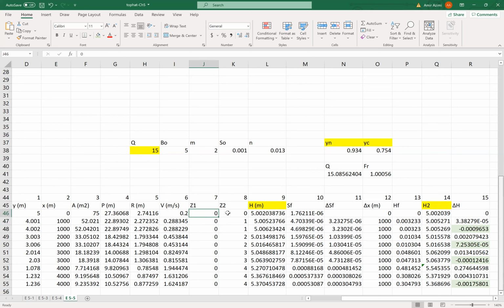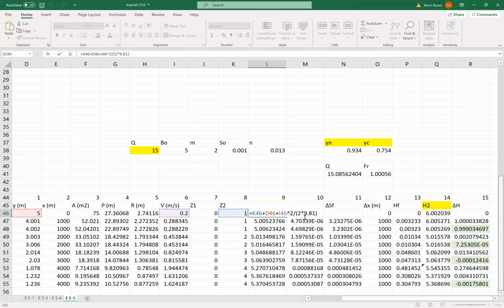Then we have the elevation, and then energy is Z plus y plus V squared divided by 2g. And then the frictional slope, which is Q squared times n squared divided by area squared times hydraulic radius to the power of 4/3, so 2/3 squared.